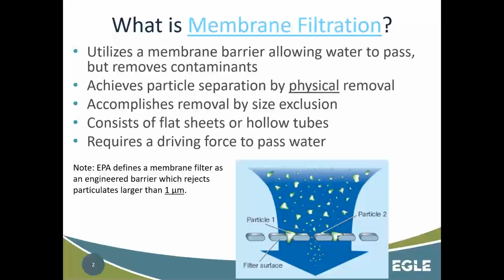It does not work on the particle attachment concept with the media filter. And also, to push this water through such a small pore space, it does require a driving force to do that. EPA's membrane filtration guidance manual says that in order to be defined as a membrane filter, it needs to reject particles that are larger than 1 micron.